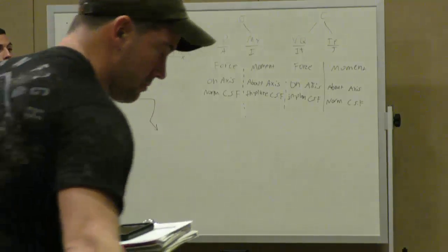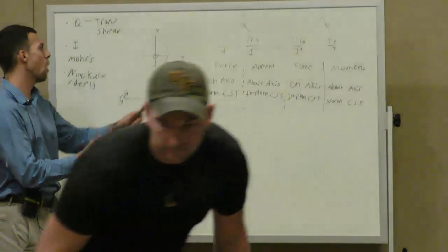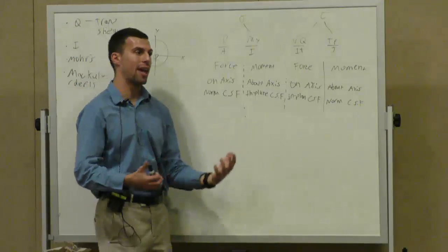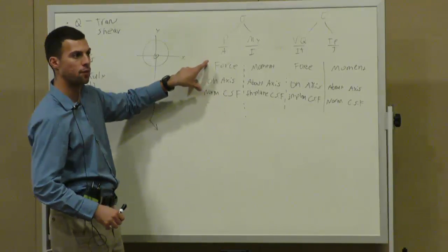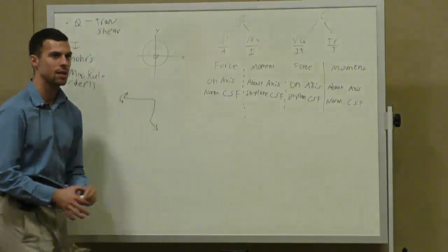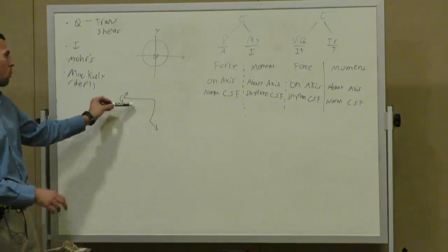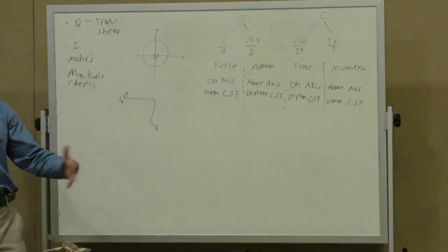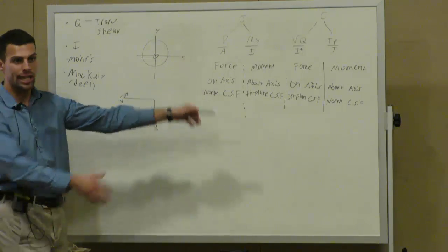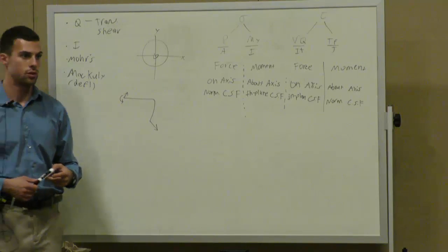Okay? And so then, once you establish those forces and moments, you then look, okay, what axes are those acting about? Where are they loading? Where are they acting? And now you have your type of load and its orientation. You can establish which equations to use. That is how you solve a combined loading problem. That's how you approach them. Start with your statics, just solve for what the moments and forces are, and then you can use this T-chart or tree chart right here to decide which stress equations to use.